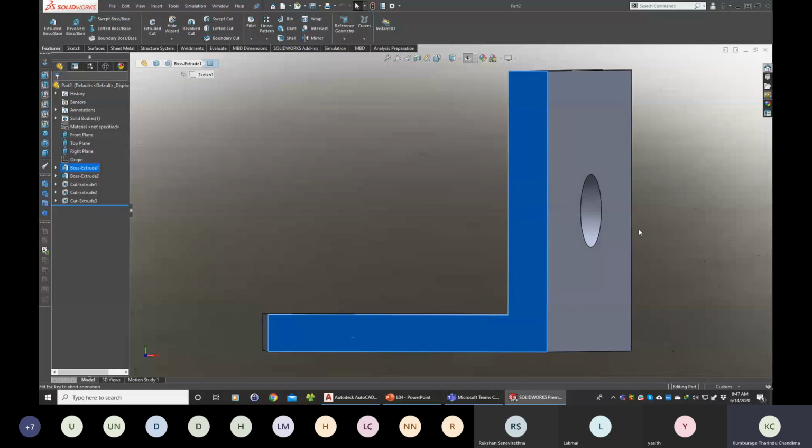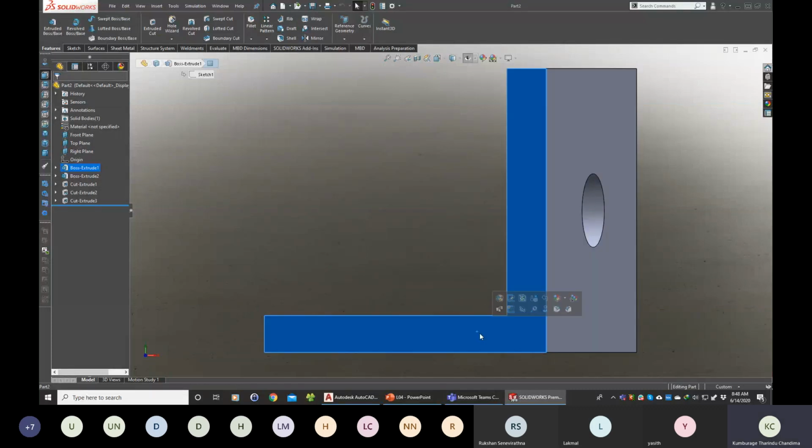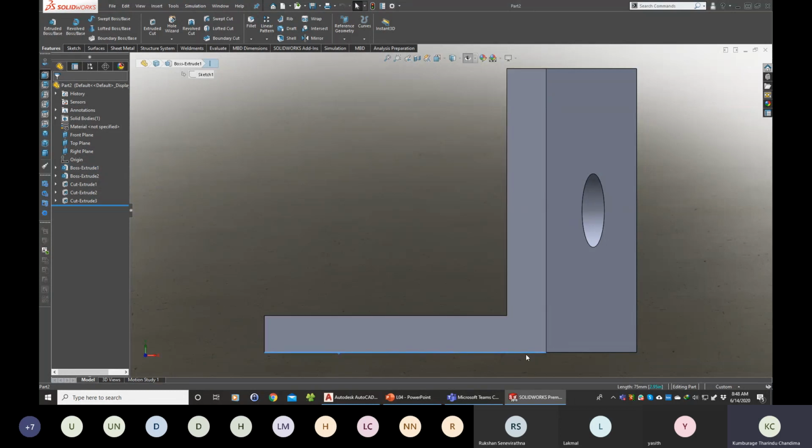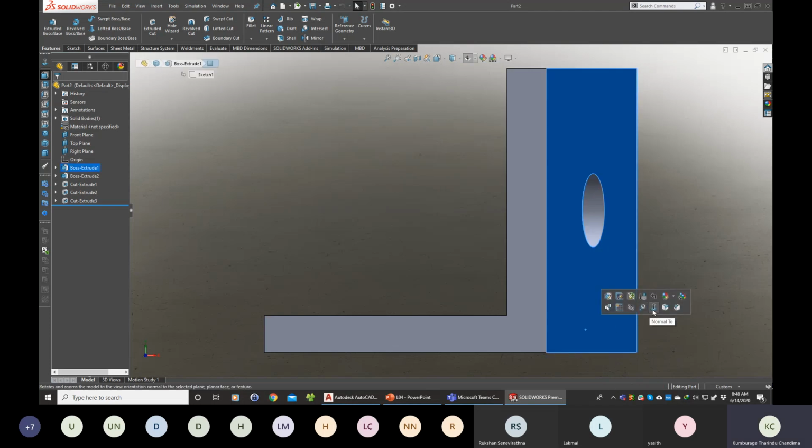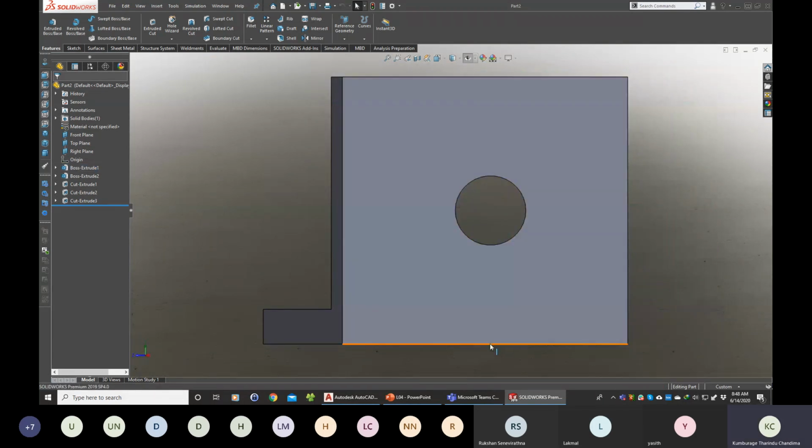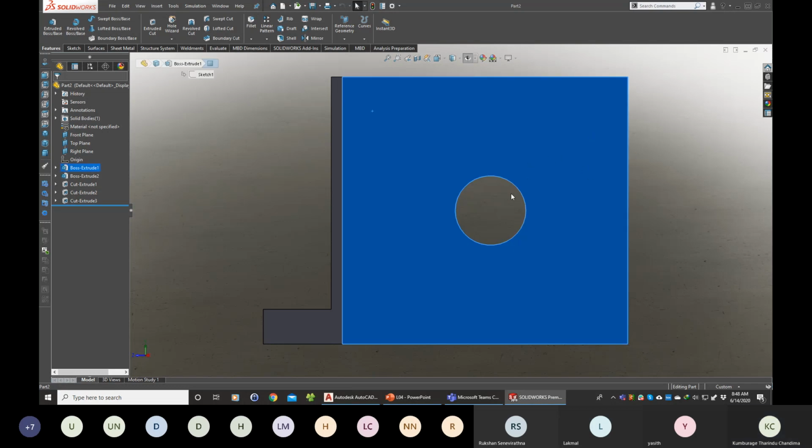From this side, it's an ellipse, but from this side, this is your true length in this feature. This is not your true length. But if you look from this side, this is your true length in this feature, but this is not the true length in that feature, right? So in a full auxiliary view, you have to draw this one as well, right? But in a partial auxiliary view, you draw this feature only.